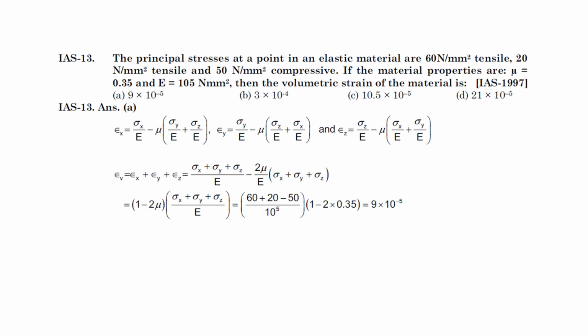In the previous videos we have seen the expressions for strain in terms of stress. Here this is epsilon x, this is epsilon y, and epsilon z. To get the volumetric strain, we have to add all three. If you add these, you will get this expression.